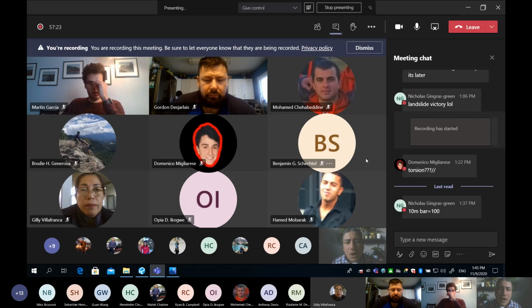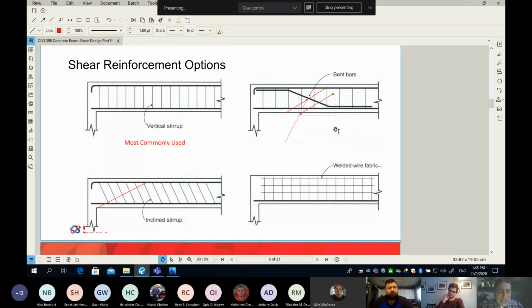And that's why the best and safest way is to try as much as you can to unify your reinforcement, make it as close to each other or the same as you can. And you can see here, if you look at my screen, for example, where those bent bars will start. So what happens if I start early or later? Is that okay? I would say the engineer who did the design for those beams that you built is not really paying attention to the quality or the communication problem that we have here in Canada.